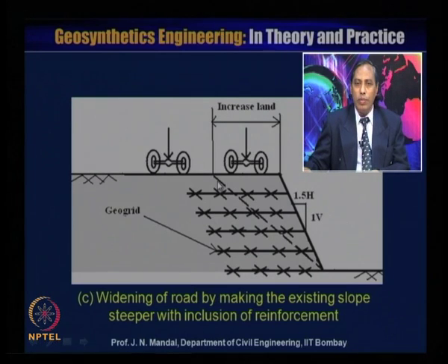So it is also sometimes required to widen the road by making the existing slope steeper with the inclusion of reinforcement material. So when it is required to increase the land, yes, you can use the steeper slope, and when you want to save the land, yes, you can do that by introducing the geogrid reinforced steep slope.